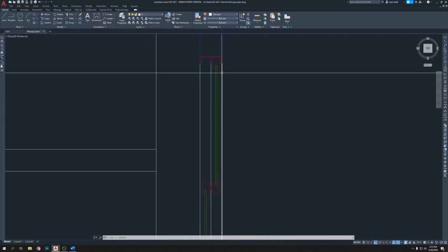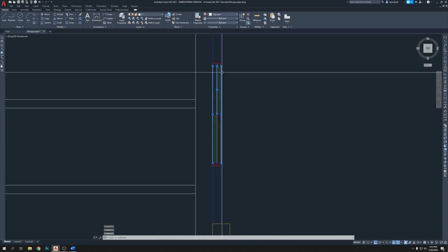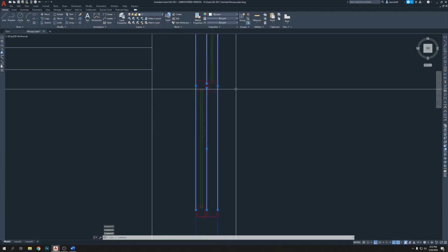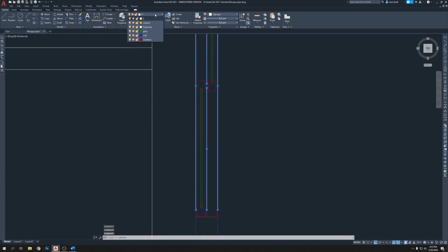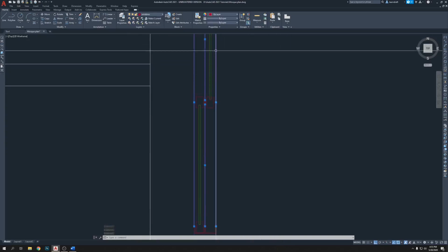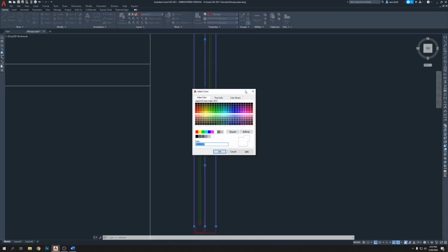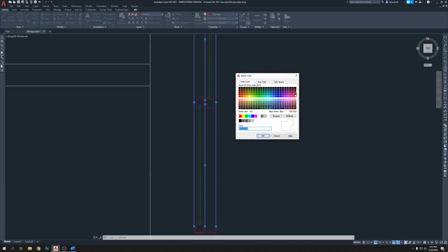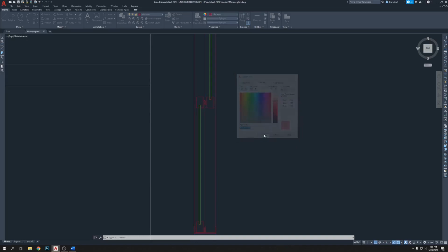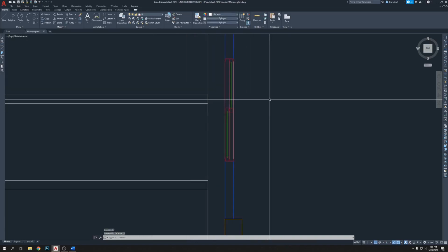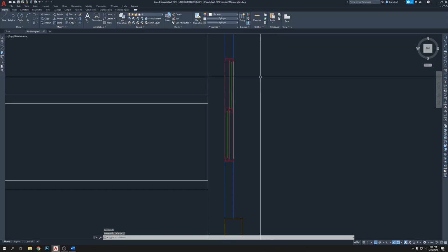Yeah, I'm going to select these three lines, make them windows, and make the color light. Windows, color, can make it light, go there, and so it was like kind of this red. If we go to the color, true color, can make it very light like this, like pink. So that's our window line, and inside the window line, this is how the window going to be.